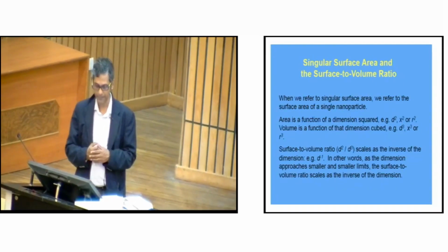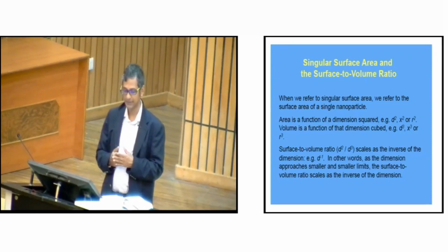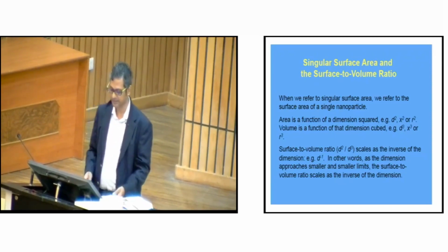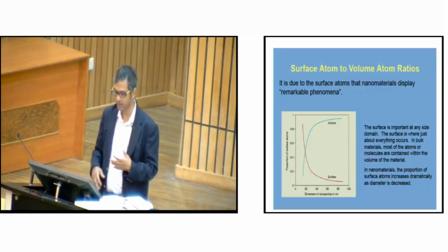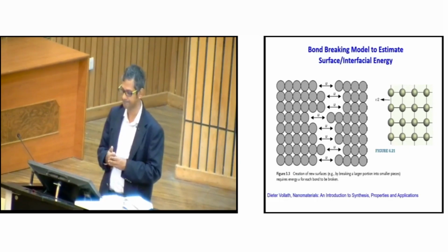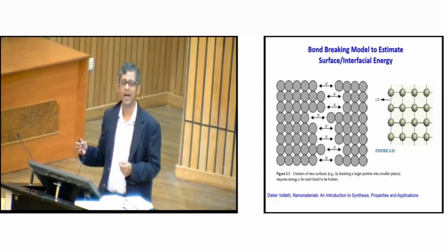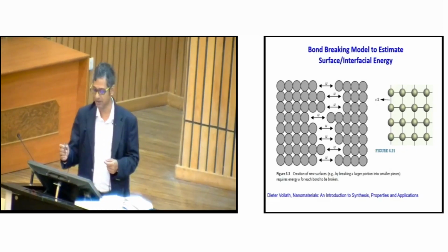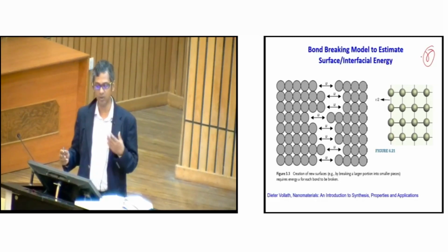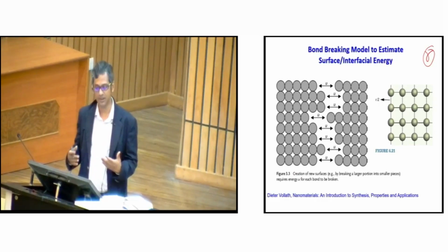You understand that? So, you have seen that the 1 by d rule is valid for spherical nanoparticles. This can be valid for many other things. But before you go into it, let us discuss first what surface energy is per se. I'll go back to the slide again. So, this picture I showed you. We only talked about how the surface area to volume ratio can change the surface energy. We didn't talk about gamma. Gamma is a specific surface energy. How does it control the surface energy of the systems? Let us look at that aspect also.